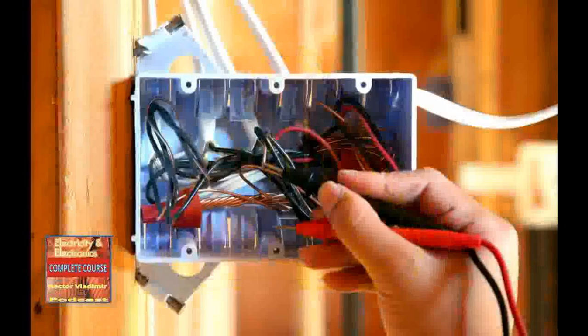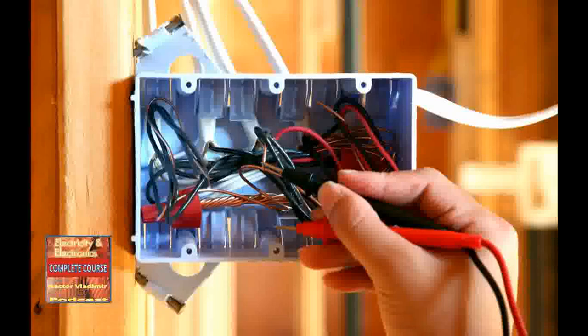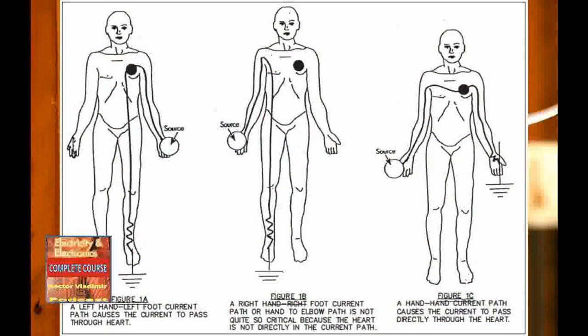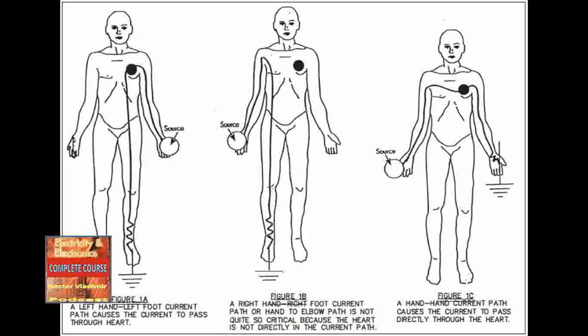Lesson in safety. One of the best ways to avoid fatal electric shock is to keep one hand in your pocket while working with high voltages. This way, any current flowing through your body does not flow through one hand and out the other. The amount of resistance through a person's body depends on many different things. For example, a resistance path from hand to foot will be higher than from hand to hand, especially if the person is wearing dry shoes in good condition. Another factor is the amount of skin surface area connected to the potential. A person's skin condition is the most influential resistance factor.